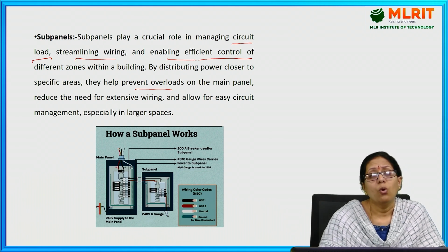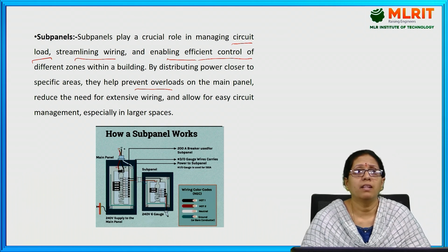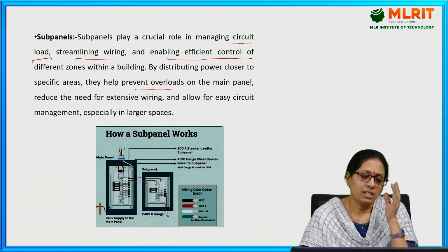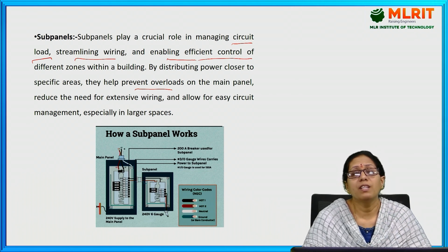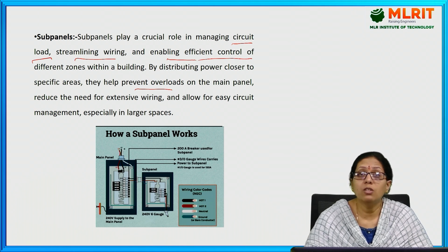Instead of connecting the whole circuit to a single panel, it is better to connect each circuit to a different sub panel, and these sub panels can be again connected to the main panel. In this manner, maintenance is easy and it is easy to detect the fault location also when there are different sub circuits.